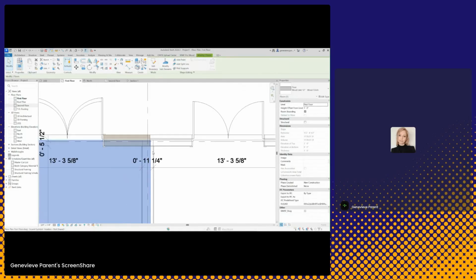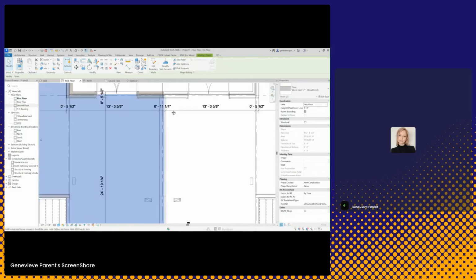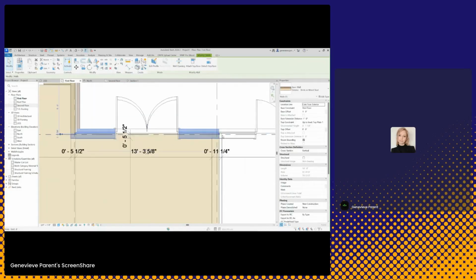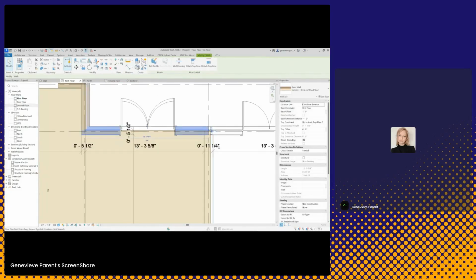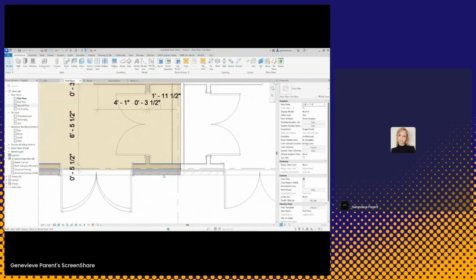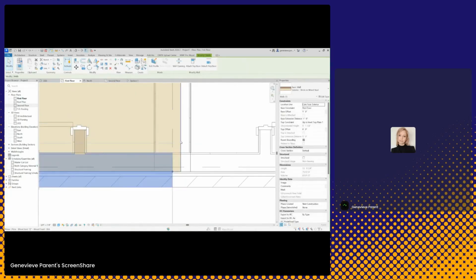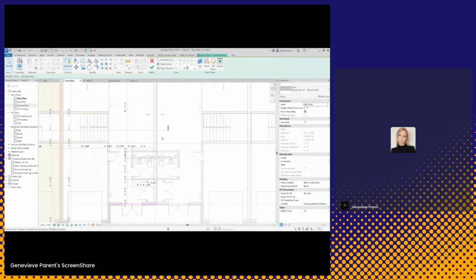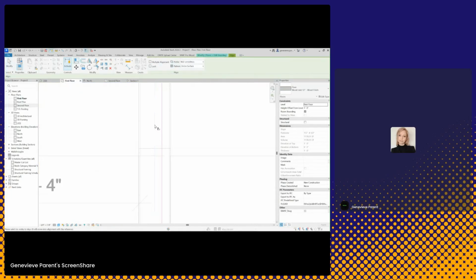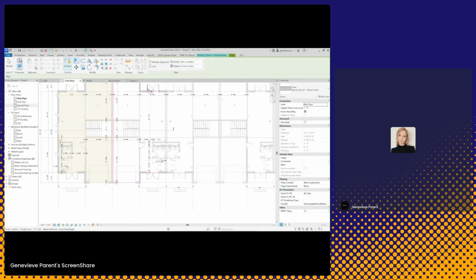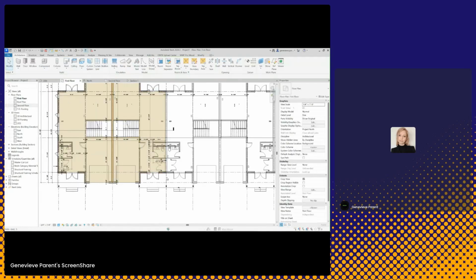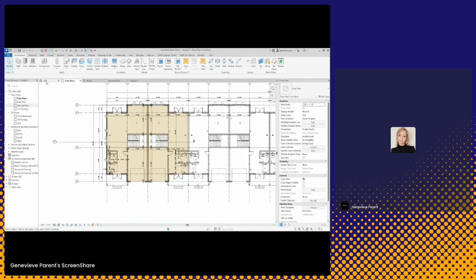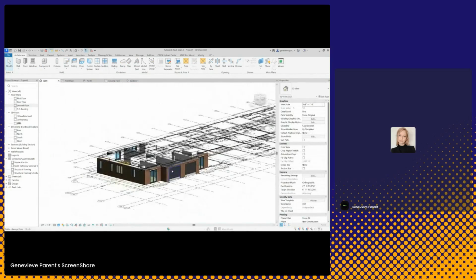So in this instance, there is a tiny, tiny difference. And that is simply because of this exterior wall. So we're going to want to just correct this real fast. We'll drag this out to line up. And we're going to fix this floor portion to just have this align with the center. And there we go. So now we have sections that can be built much faster.